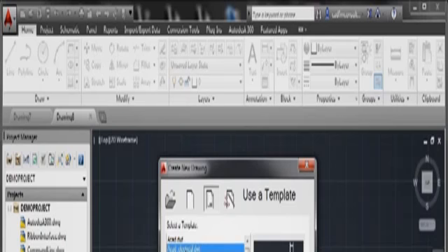Now the electrical ones, strangely enough, don't have a description. That's because it's in the title. AutoCAD Electrical IEC means that it's metric European, so that's a metric template. AutoCAD Electrical.DWT without the IEC or the ISO is an imperial inches default electrical template.